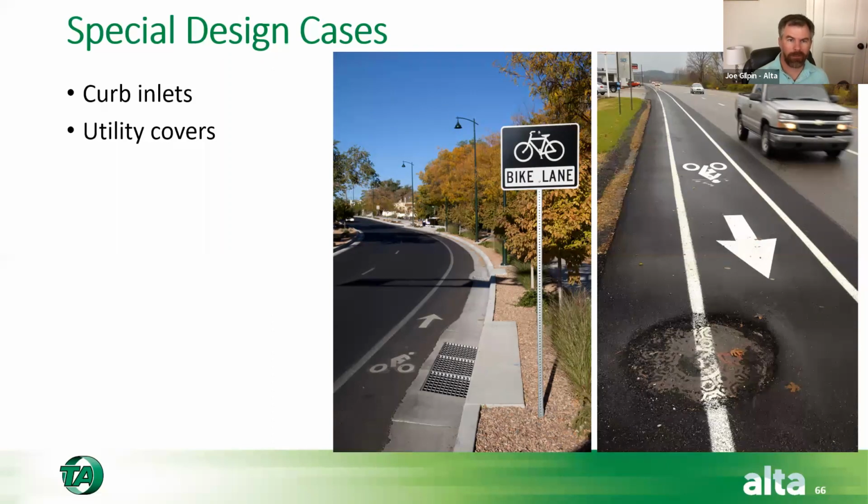And then your inlets, A, do they have bicycle friendly grates on them, and B, how far out do they project and what type of cross slope do they provide? So those are all things to be thinking about. And thankfully, this really has been an area where we've made a lot of progress over the last 20 years. I remember some of these, I could literally get sucked into inlets. I remember if I tipped over riding as a kid. And now most of our inlets are really in pretty good shape overall. So hopefully those aren't problems.